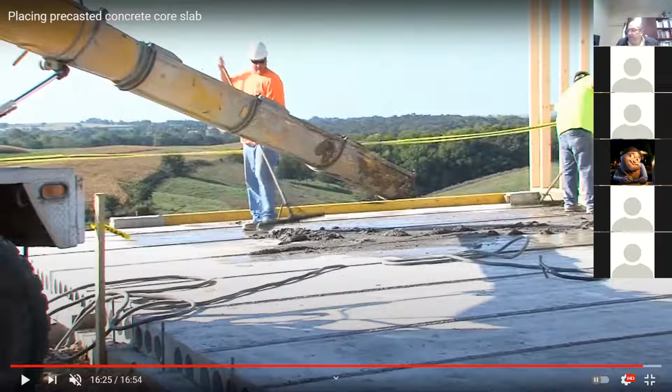What's the reason for the trimming? Is it just to make it fit better? Yeah, to make it fit, exactly. This is a beautiful thing about pre-tension. For pre-tension, you can trim it, cut it, or notch it, you can do anything you want, because you have full bond between the cable or tendon and the concrete. In post-tension, you cannot do this.